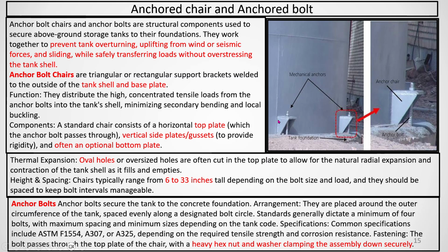Because the contact along with the shell is more here: this side with the tank, this side with the bottom plate, the annular plate. So the foundation bolt load will be distributed over this much area of the shell. There are so many foundation bolts like this.